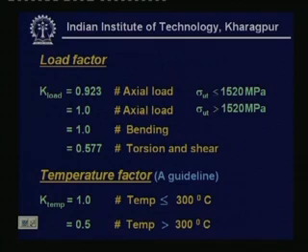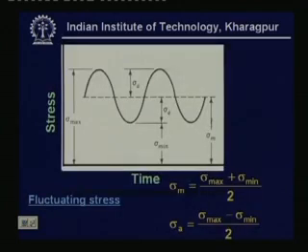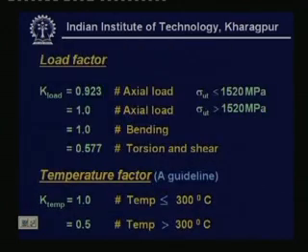Now, we can remember that we got such values when we considered the maximum distortion energy theory in our earlier lectures. We found that if we know the sigma yield point, then the corresponding tau yield point comes out to be around 0.577 sigma yield point, and this result is also very close to the distortion energy theory.